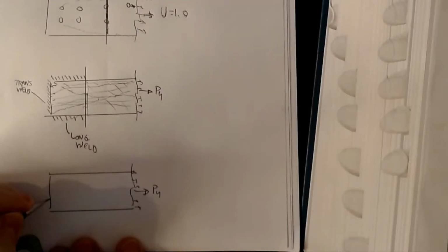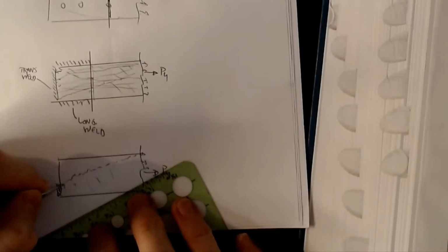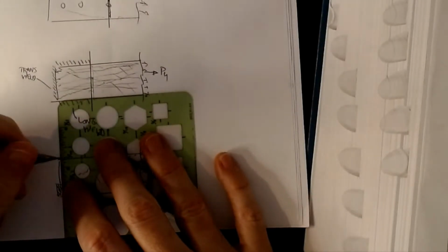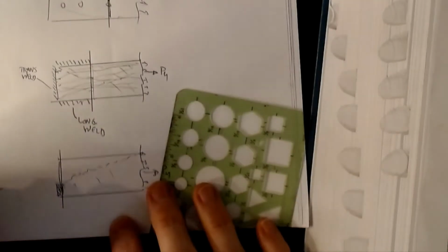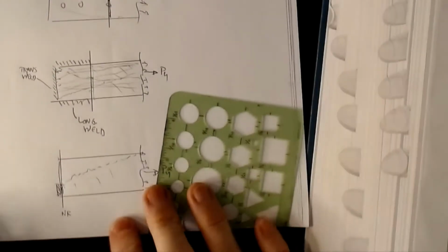Okay, but now I only weld a portion of it. Well, think about what's happening with the load. When it was the full length, the load pretty much went straight across, but now it's starting to do something like this. So here's my effective area, and my net area for this calculation would be here. We've got to do something to calculate that area, and that's what this provision in case 3 is trying to do.